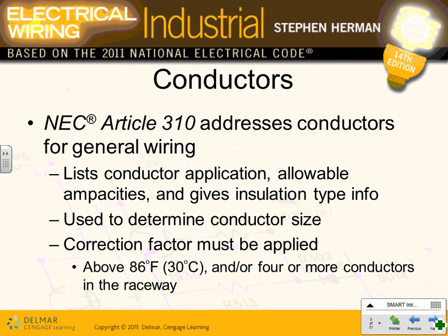Yeah, well, it's better discovering it at this point than energizing and getting yourself a ground fault. Nobody's going to get hurt, but you burn part of the equipment and you have to go replace it. Measuring it and finding the ground fault or short circuit, guys, is much better than discovering it downstream.